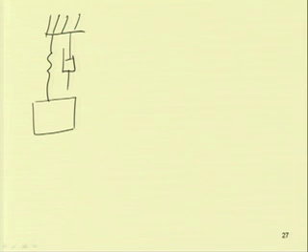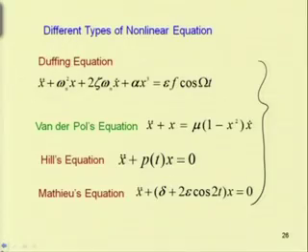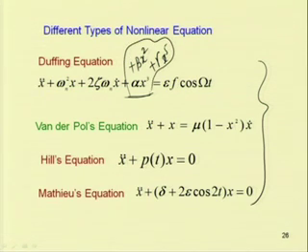So, in this Duffing equation type we can have this quadratic nonlinearity or we can have cubic nonlinearity. So, this is cubic nonlinearity. One can add quadratic nonlinearity or quintic type of nonlinearity, what already we have seen, gamma x to the power 5. So, by adding different types of nonlinearity to the system, we can write this Duffing equation.